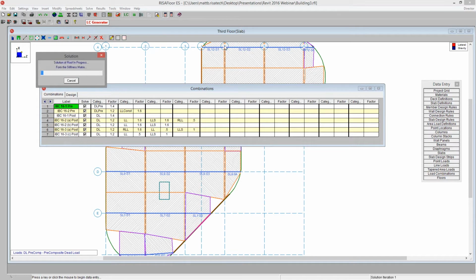And so what this is going to do now is up on the beam floor, it's going to run through a load attribution for each one of those beams, and it's going to optimize the member sizes for them. So it's going to try out every single different type of steel size to find out what the most optimal size is in terms of code check versus self-weight. And then what it's doing is it's performing a finite element analysis on the 2 concrete slab floors.